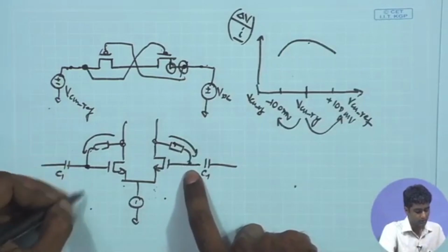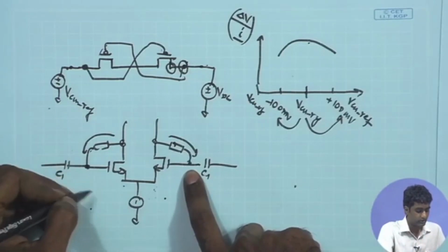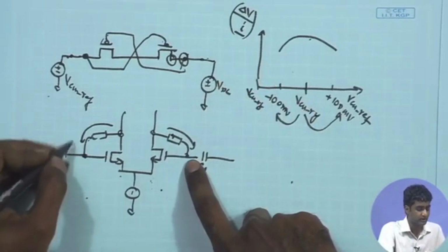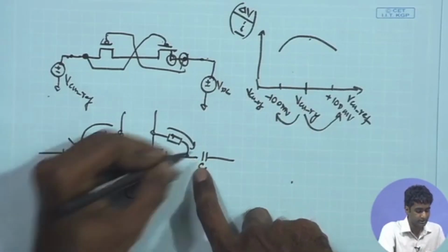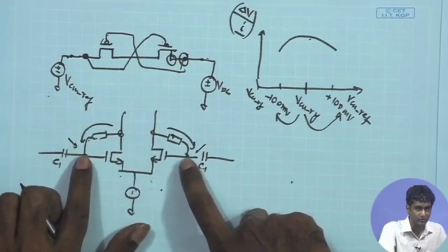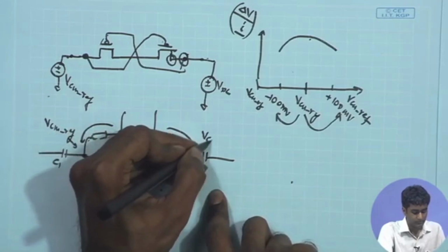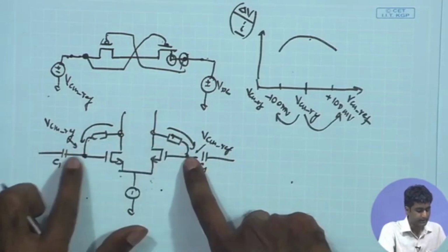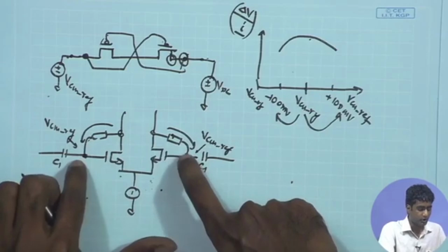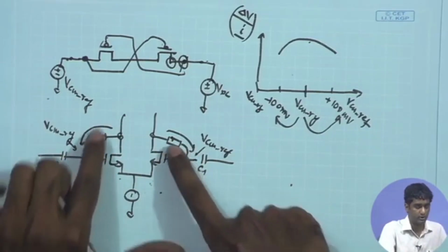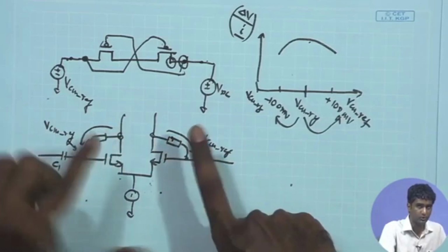So, one of the standard techniques to make it fast is to have some initial conditions. So, in the simulation, if you are putting some initial conditions, so that these two potentials are initialized to the value equal to VCM ref, in that case, you will not be dependent upon this resistor values to set up this value equal to the VCM ref.